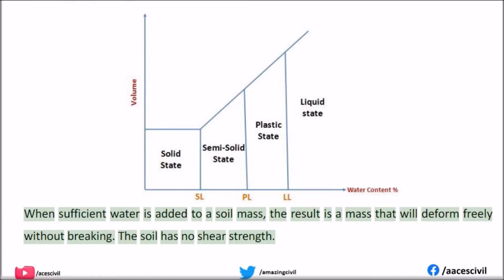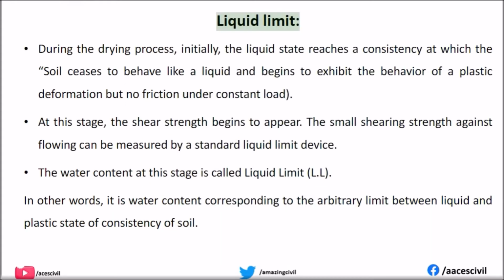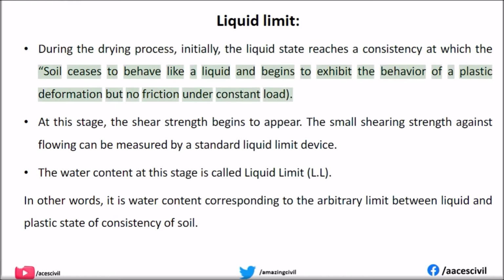When sufficient water is added to a soil mass, the result is a mass that will deform freely without breaking. The soil has no shear strength. Liquid limit. During the drying process, initially, the liquid state reaches a consistency at which the soil ceases to behave like a liquid and begins to exhibit the behavior of plastic deformation under constant load.